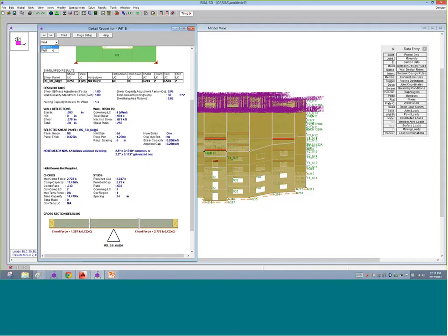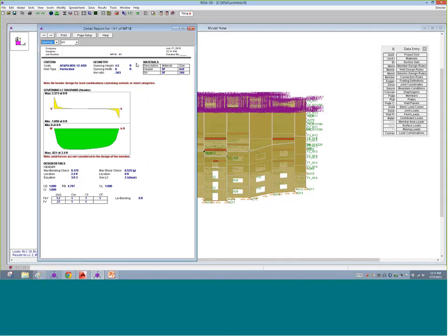For this perforated opening, you go to an opening report, and here it'll design this opening for us. So we're going to see what the header requirements are. We're using a very large header. It's 6 by 8, I think we said. So here's a 6 by 8, so it's pretty big. You're getting a 0.17 unity check. I wouldn't imagine that would fail unless we had some serious point loads coming through. So you've got the openings listed there.